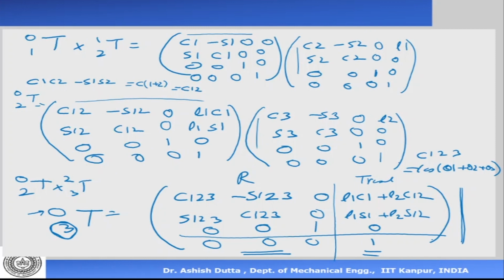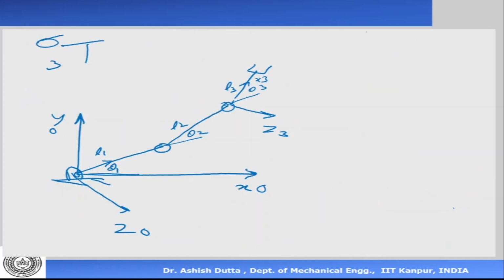That's the question. If you look at this side, this is the distance del x, del y, and del z, the distance between the origins along the x-axis, y-axis, and z-axis. If I project it down here, this is my theta 1. So what is this distance? This is del x, which is equal to L1 cos theta 1 plus L2 cos of theta 1 plus theta 2, which is correct.